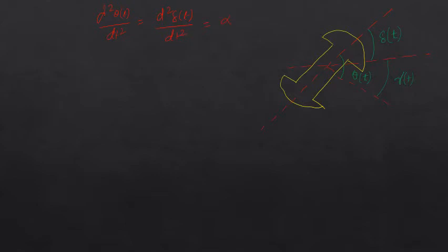Now if I put this value in our swing equation, we had m into alpha equal to Ps minus Pe. Now m into d square delta t upon dt square is equal to Ps minus Pe. For more clarity, I can write d square delta t upon dt square is equal to Ps minus EV upon X sine delta, where this term is our electrical power.